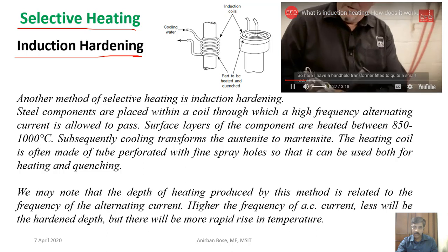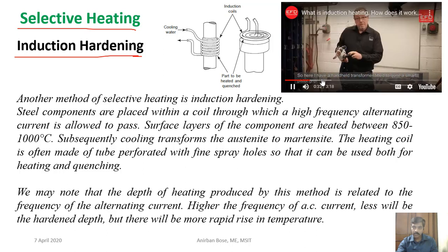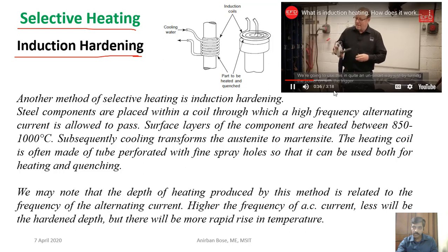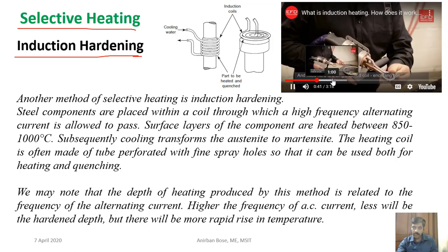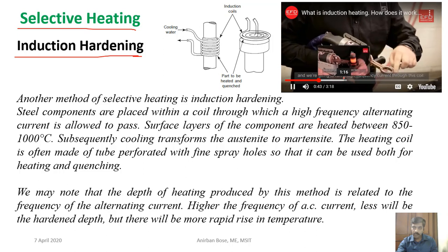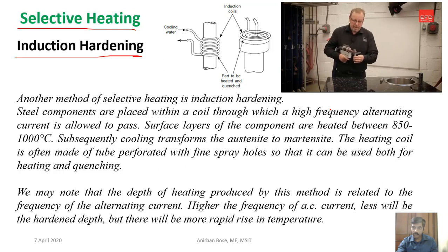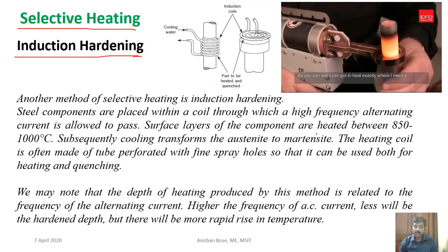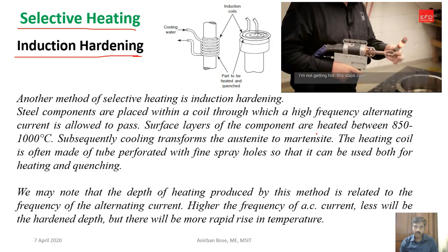Let me show you. Here I have a handheld transformer fitted to a smart pistol grip. We turn the power on with the trigger, and fitted here is a single turn encircling coil, and we're going to run a high frequency current through the surface of the part, giving us heat. So here we go. As you can see, I can put in heat exactly where I need it. I'm not getting hot, this stays cold,